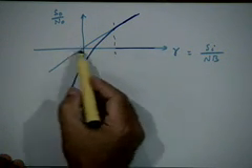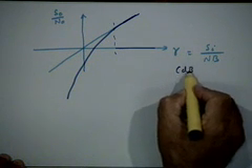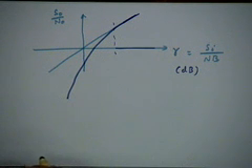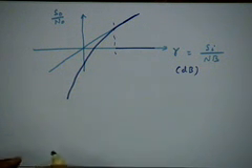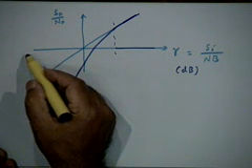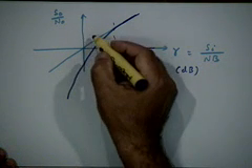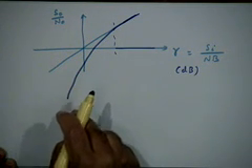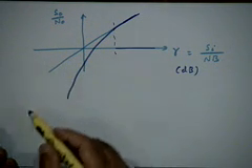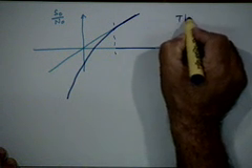Incidentally, you should have asked me what the negative axis here denotes. I am plotting this in decibels, so you can have negative dB values as well as positive dB values. Of course, signal to noise ratio in absolute terms will always be positive because it is a ratio of powers, but when you take it in decibels, you can have a negative value of the signal to noise ratio because it is 10 log of the actual value, right. So this is the behavior you are going to see in the envelope detector, and this kind of phenomenon exhibited by the envelope detector is called the threshold effect.